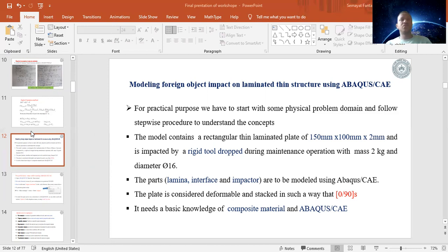And if we want to introduce an interface element between plates, at the interface, to simulate the delamination at the interface, I have to create also an interface layer with a very thin thickness, a maximum of 1/10 of the thickness of the lamina. I will discuss it only theoretically, but the main case is we can create it and give dimension.